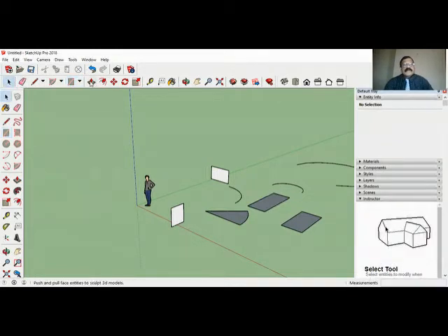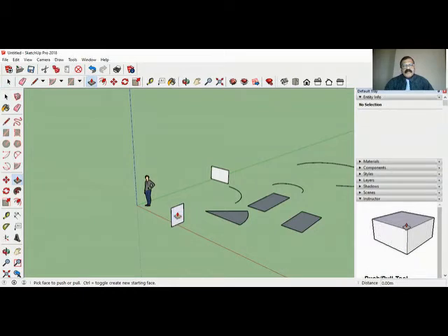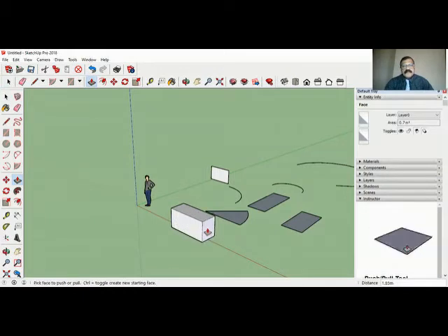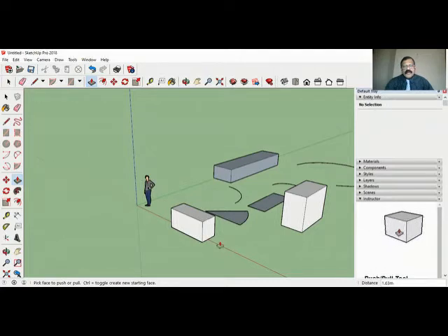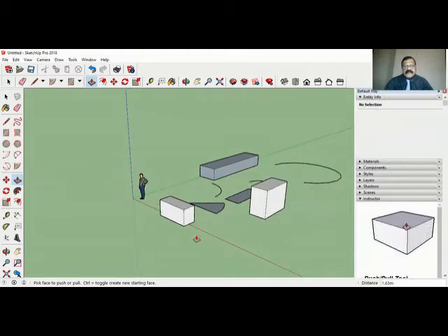So when I extrude, you see what happens? This is perpendicular to blue, red, green. So whichever axis you want to draw, you use the arrow key. Right arrow key for red, left arrow key for green, and top arrow for blue axis. So it's very important.